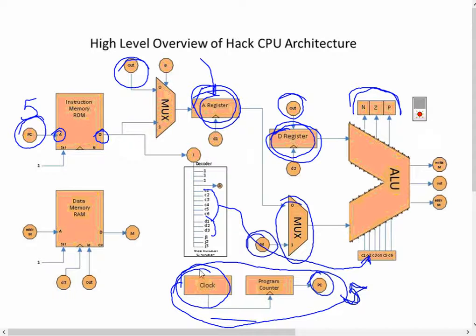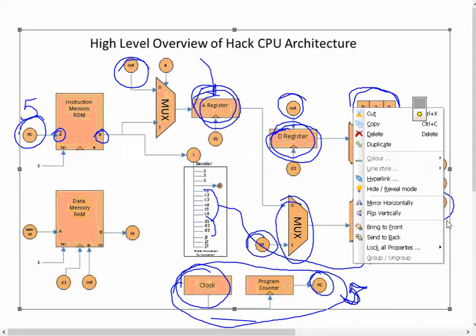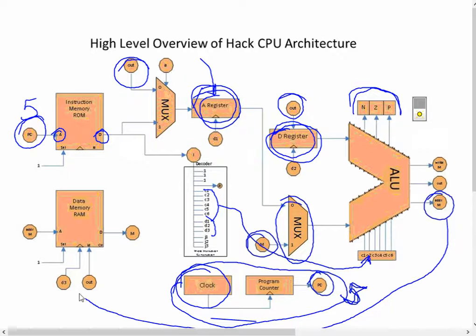So this is giving us an idea of the control logic, the role of the decoder, because what the decoder is doing is bringing these signals, this instruction in, and it's allowing us to send the signals to the appropriate source. Okay, the one area we haven't really addressed a lot is this whole concept of RAM. And one of the things you notice I have coming out here is address M. So that A instruction, one of the places that I can actually route it to is I could specify a memory address in there, and then when I route it, it will actually route it all the way over here to where this address M is. And this is how I'm actually able to read memory.